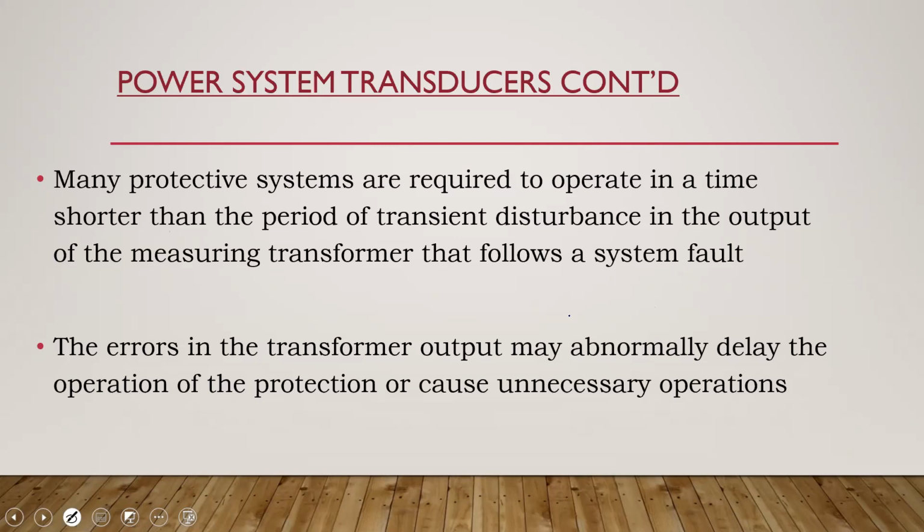All right, so what we are saying here is that you all did networks too. You all did transients, eh? So you know what a transient is. So what we are saying here is that the time for the transient to die out can be much longer than the time that we need to clear the fault.